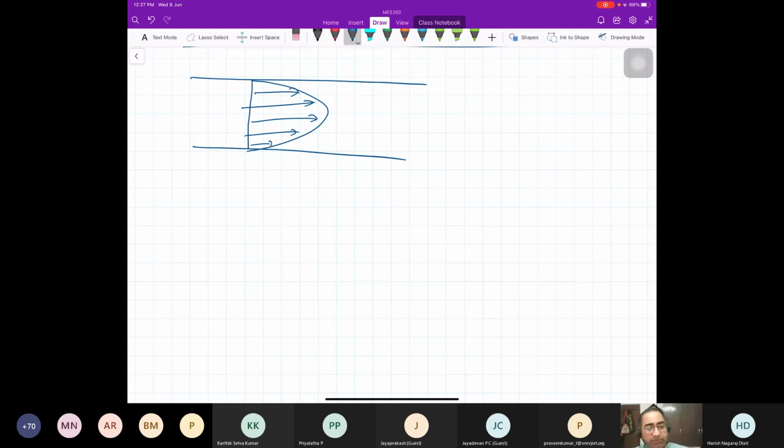It's a bridge which was open to the public, and within a few months after opening, heavy wind started flowing, and the wind actually exhibited fluid elastic instability and it collapsed, because there's a coupling between the elastic modes of the bridge and the fluid modes because of vortex shedding, and this coupling led to massive amplification of the bridge oscillations.